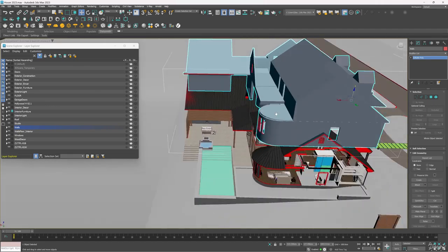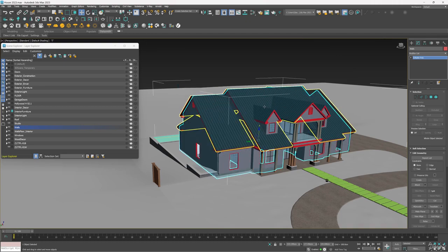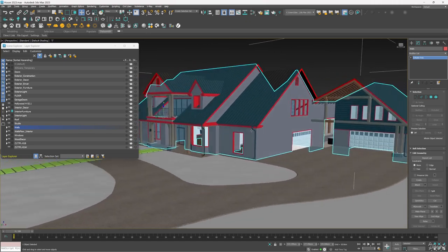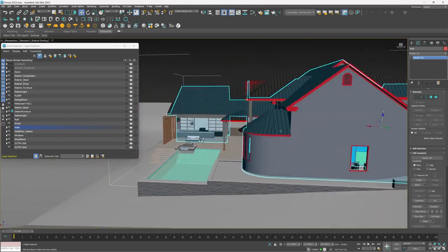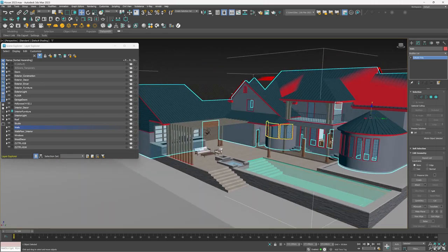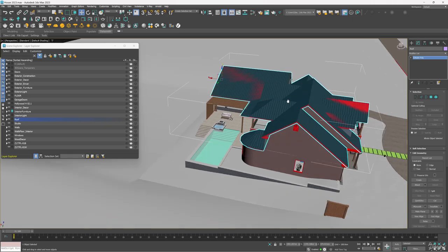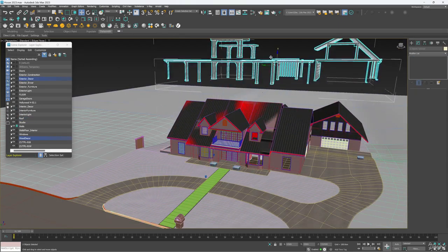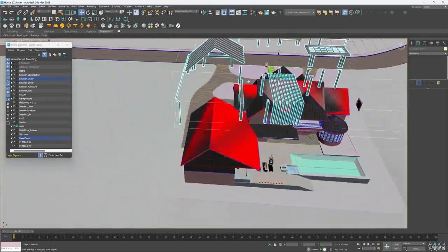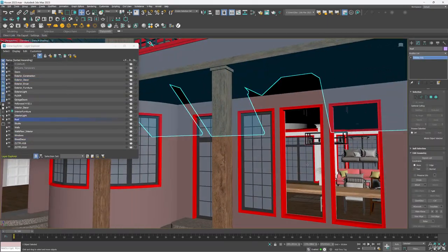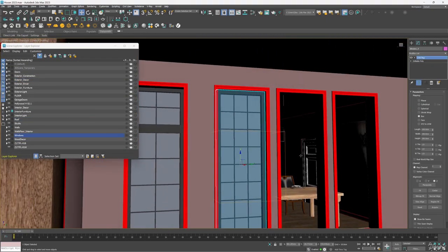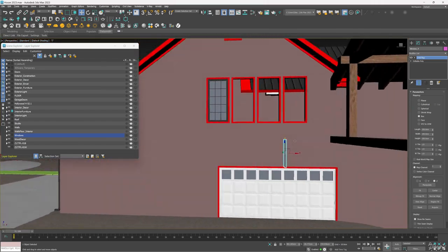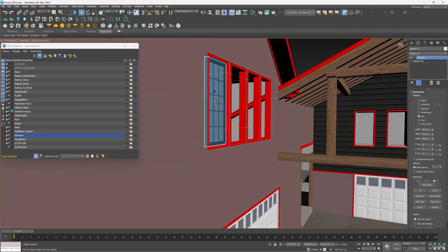I merge all the walls into a single mesh for better optimization. By the way, in the form of a single mesh, your client can transfer the 3D model to you when exporting from SketchUp, Revit or Archicad. All elements of the roof are merged into a single mesh, as well as facade decor elements and some other small objects, for better optimization. Windows are not everywhere. For better optimization, assets with multiple copies should be duplicated in Unreal Engine. I'll show how this affects performance in the next part.